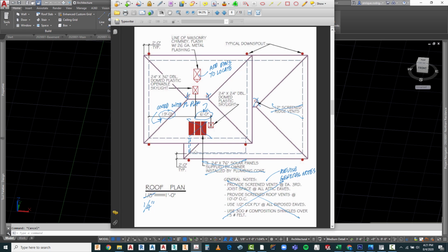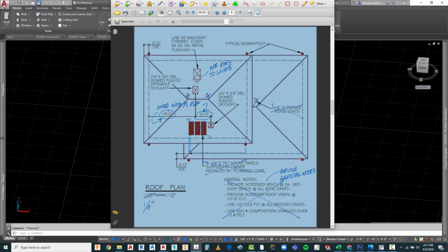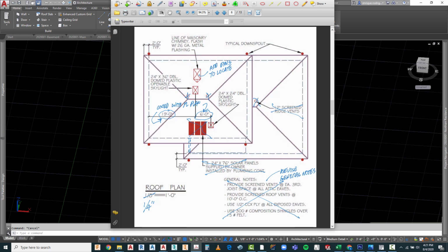There's a couple things that we need to do to the front porch to make this work. So this part of the roof that's providing shade from the front porch still needs to rest on something. So there are two columns here that are supporting a wood beam coming across here, and I'm going to go ahead and bring the wood beam coming out in here. This also tells us that our overhangs are 2 feet.